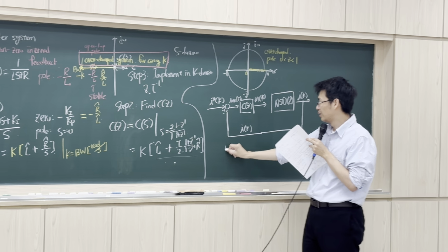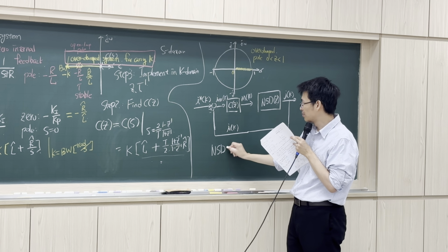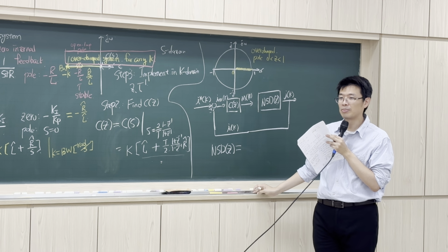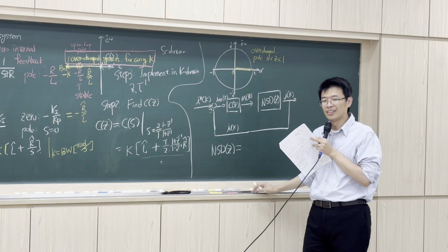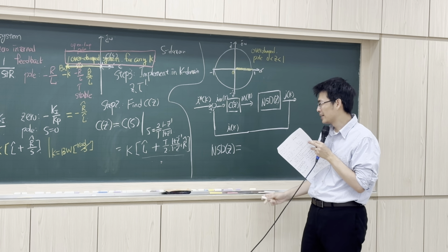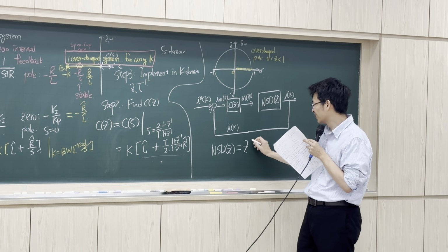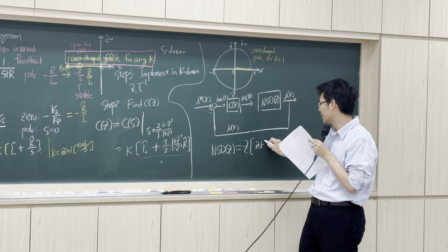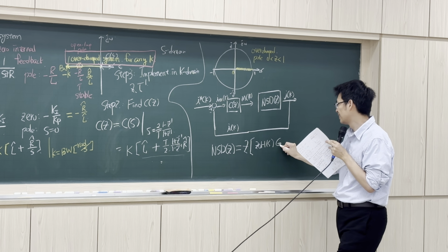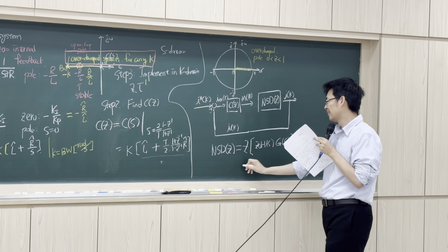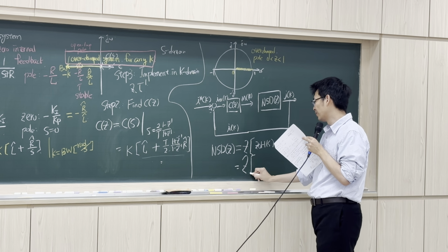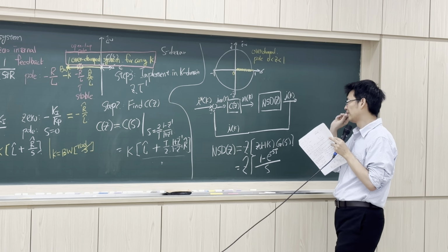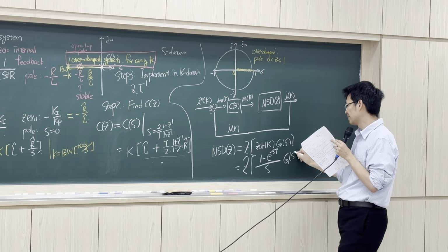So from this block diagram, can you show me what the corresponding G_d(z) is? You can just use the Z transformation of the zero order hold, (1 minus e^-Ts) over s, times G(s). So it's equal to the Z transformation of the zero order hold S domain transfer function times G(s).